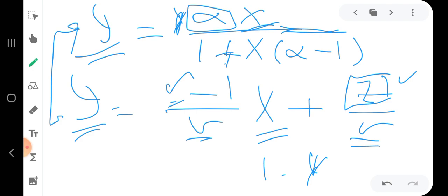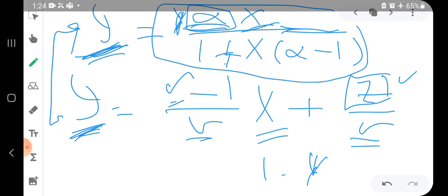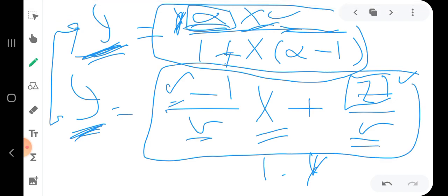It is like mathematics when you have two equations and two variables, so you can solve them simultaneously. For the case where the relative volatility is given, you can solve them analytically, or in other words, algebraically. Where you use algebra, you can say that this is y and this is y, so this side is equal to this side, and you can use a solver to get x, and then after you get x, you can substitute in one equation and get y. This is for the case where the relative volatility is given.